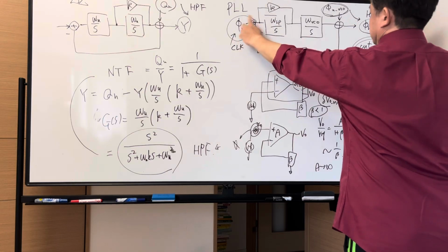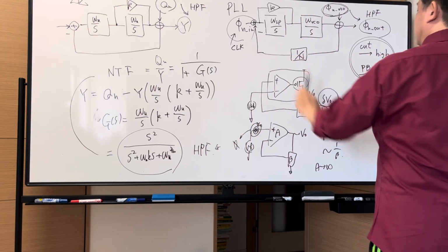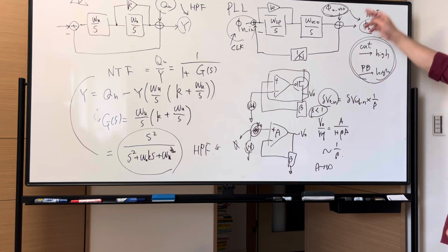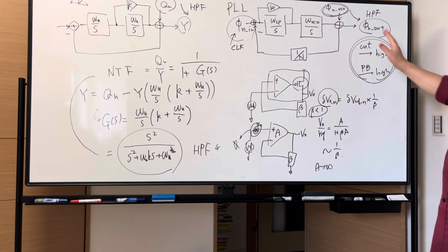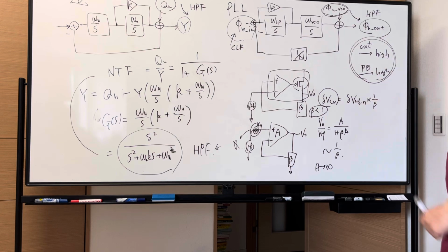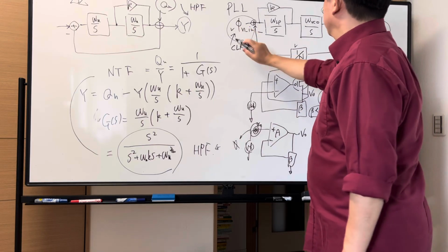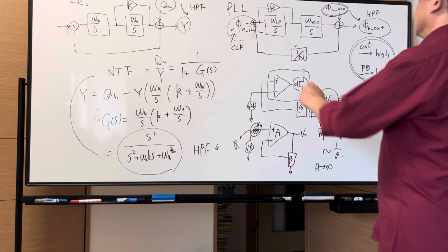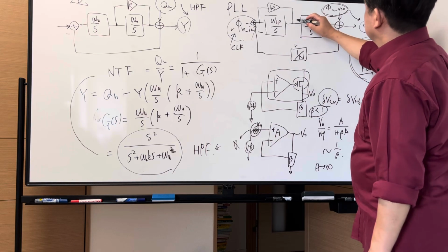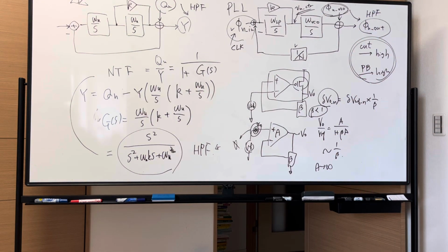While we remain with the problem of this input phase noise, if the input phase noise is negligibly small, we can apply this procedure for the design. Of course, there's an appropriate moderate point of the loop bandwidth because it has some noise. The clock has some noise. Of course, the phase detector and this control point also make some voltage noise from the charge pump current.